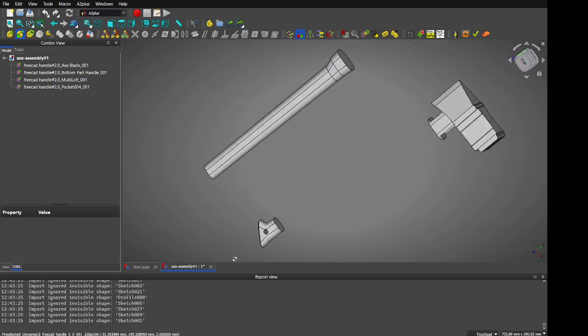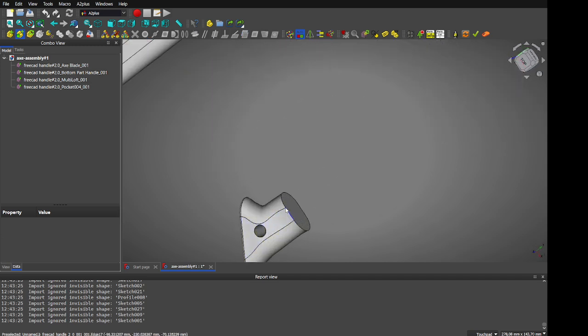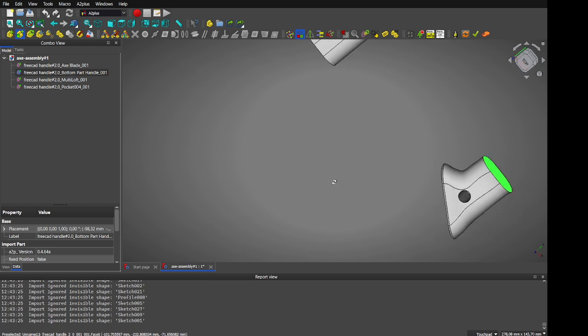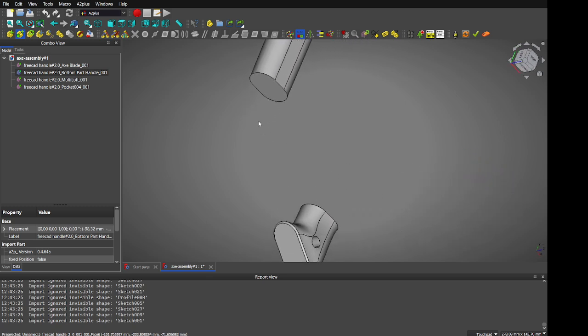In this way we will use the connection. So you select the first surface, then you must move around the axis, and by holding the control key and selecting another part, you can see the constraints allowed for this operation. For us, these are 4 constraint operations.